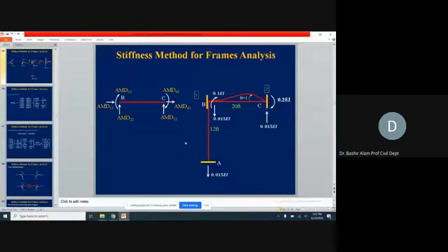AMD 1 to 2 to 3, you can see at joint B, at joint C again you can see this 4 to 5 to and 6 to. From where will you be getting these values? You will be getting these values from the sketch, which we already drew for the generation of the second column of the stiffness matrix. And accordingly, you need to pick its values from here. These are the values for BC. So now this will complete the second column of the AMD matrix.